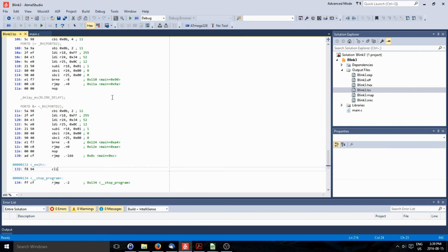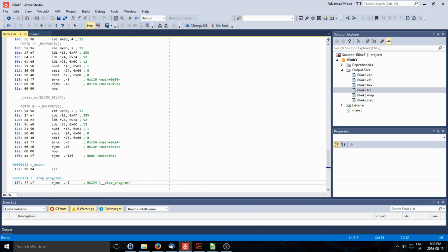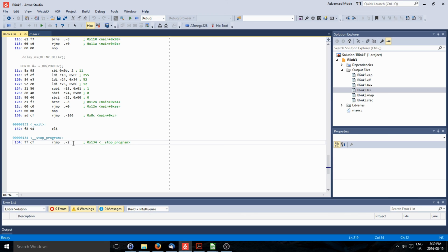But you don't want it to do that, because obviously when it's sitting here, it's not doing anything else. It's wasting time. But it's put here as a safety measure, so that if something happened and caused your main routine, your main function, to exit, you don't go off and execute some weird code. Maybe it's running something and it turns a motor on that it shouldn't, or whatever. So the idea is to trap the processor here so it doesn't do any damage.